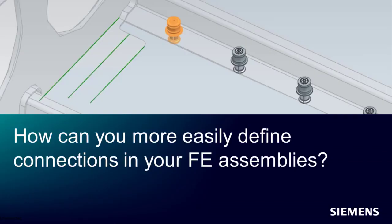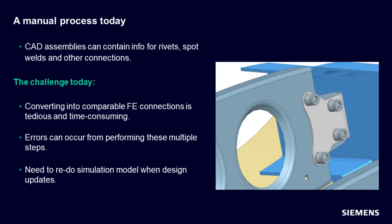Building an FE model from a complex CAD assembly requires many steps. One of the most challenging steps often is in the modeling of different connections between components. This is challenging because there can be hundreds or even thousands of these connections, and there's also many types of connections like rivets, bolts, spot welds, and seam welds.